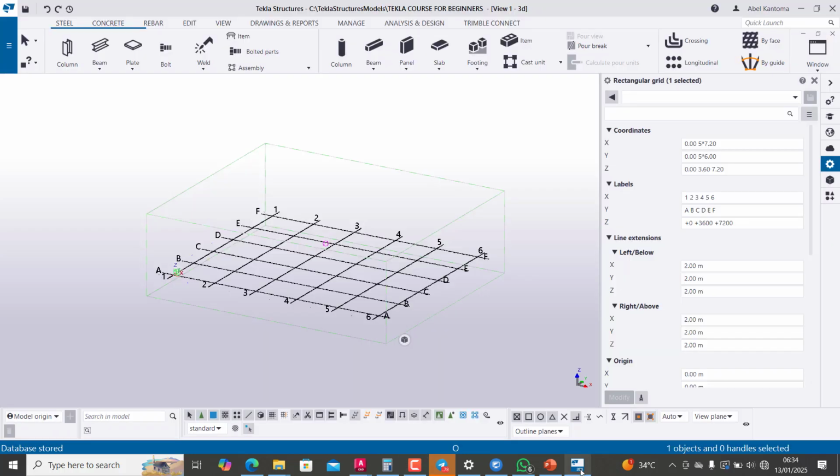So if that is correct, on Tekla what we will do is come down here, and the first point is 0.00. I will leave it as it is, and I will type 2 times 12.5. I believe you understand what that means. So at 12.5 we have a grid, at another 12.5 we have another grid. That's basically what it means.